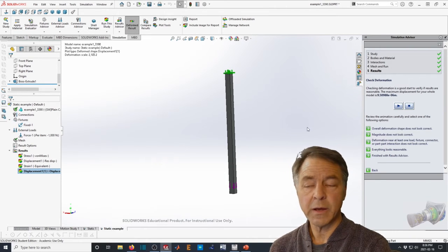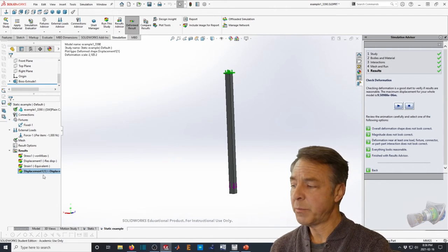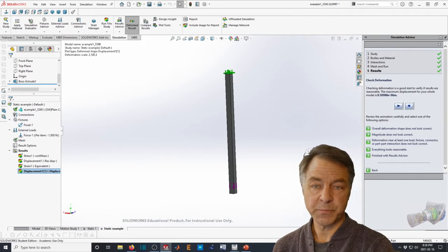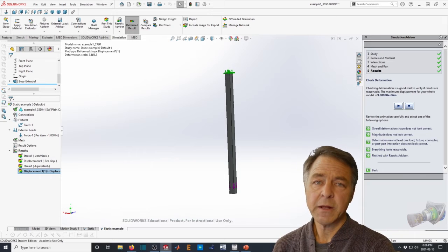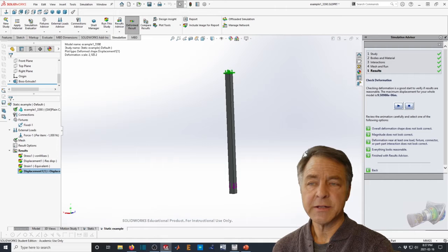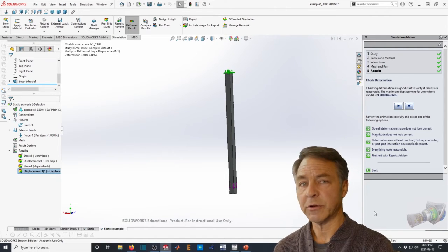Well, we're going to look at this with some other tools, but one of the things that we might want to do is change the size of the mesh and see if that number changes. But first, let's cut away and do some hand calculations and say this was a really simple model. Can we actually compare this to hand calculations and come up with a similar answer?